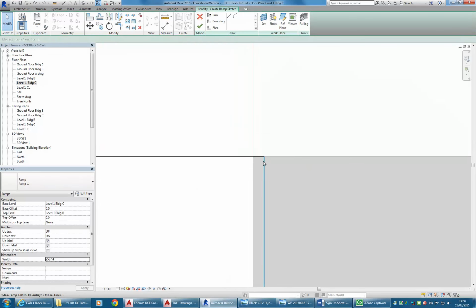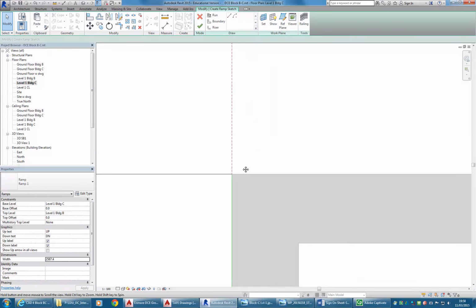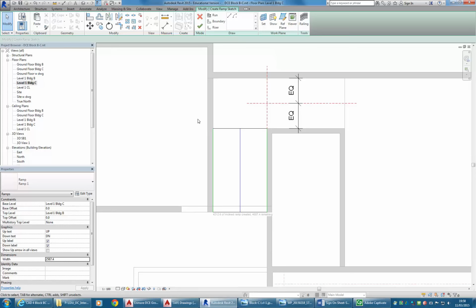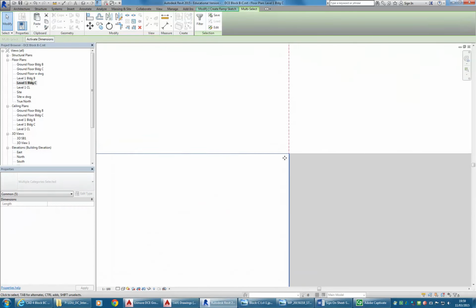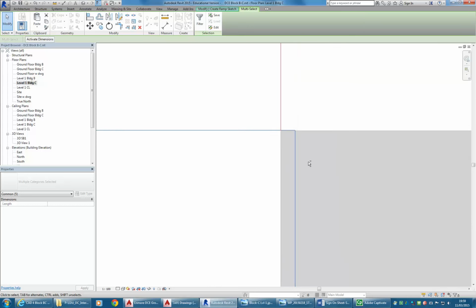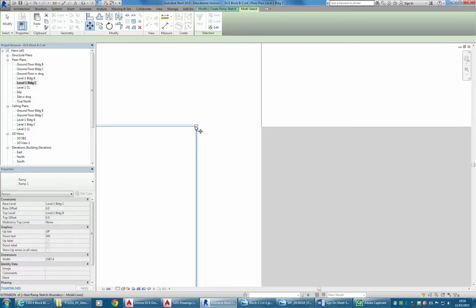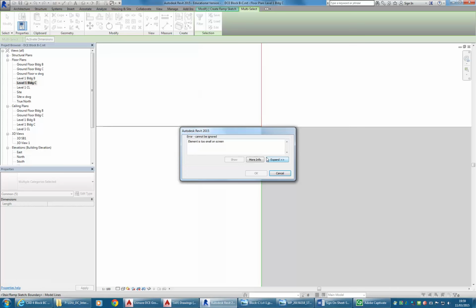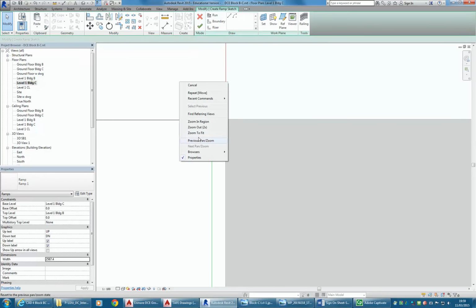Yeah, it's a bit painful when that happens. It's not going to let me create this while it's out by just that little amount, but also, because it's Revit, it won't let me move that. So I'll try just using the arrows, take it to the left and past the wall, and then I'll use move and try and snap it back. Yep. It's a bit painful when Revit does this, but it's just something you have to live with.